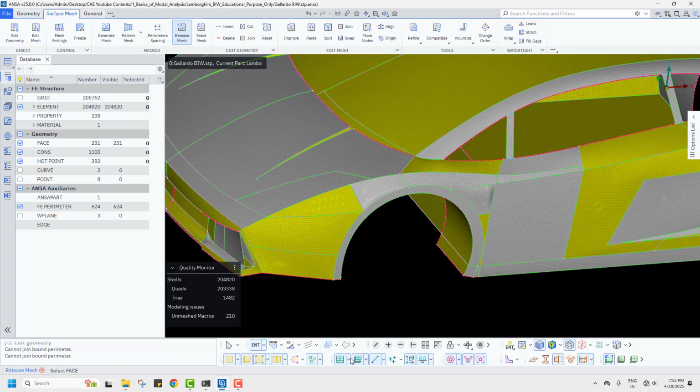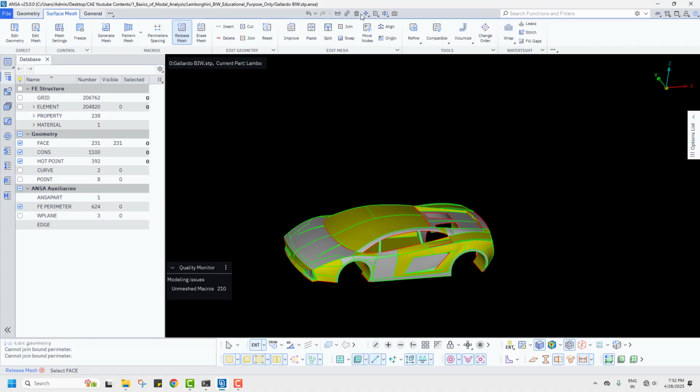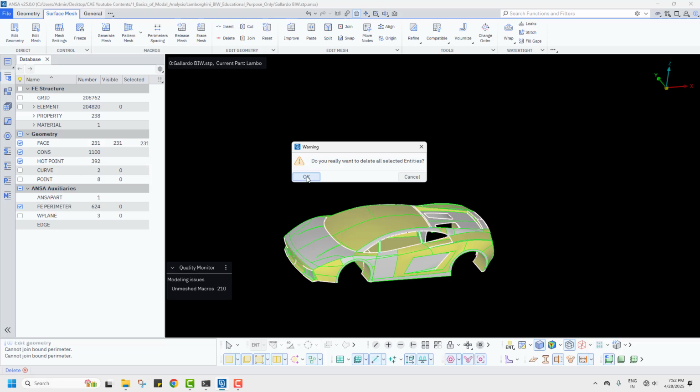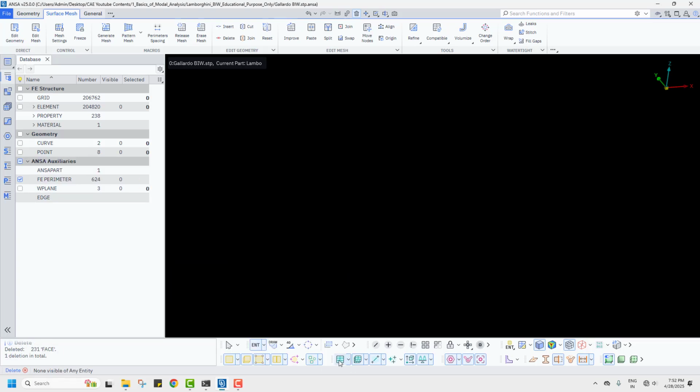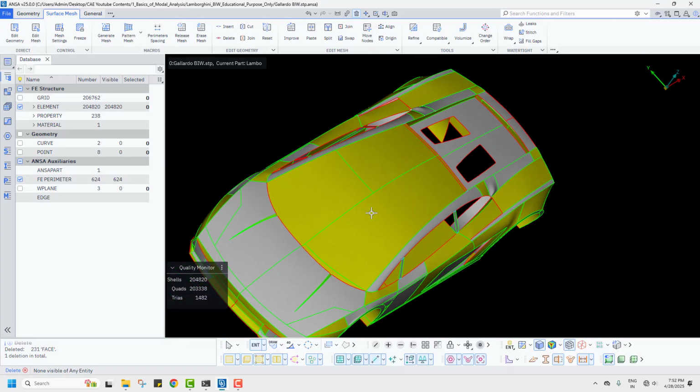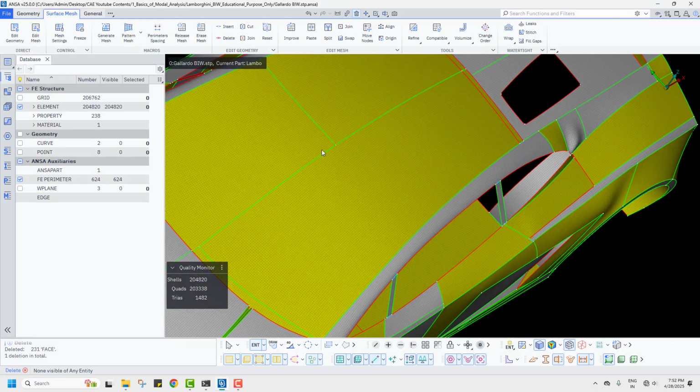This is the CAD. Okay, now for my reference here to run the model analysis, I just need the FE. So I would like to simply remove the CAD out of it now. Okay, now I would like to have a split line, so you can just create it from here to here. I would like to split.